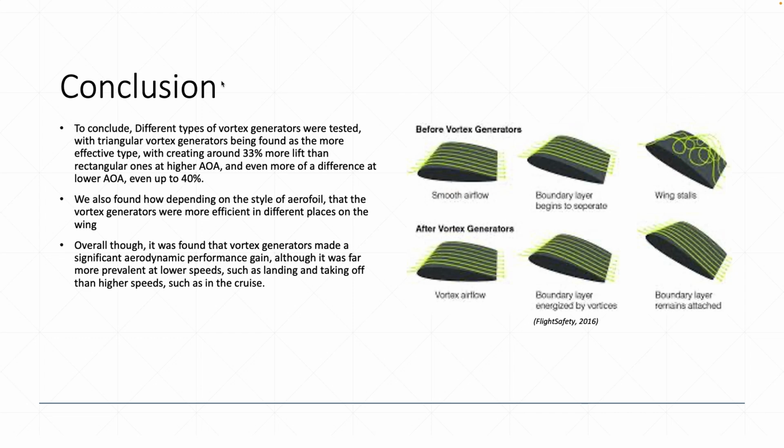So just to conclude, vortex generators provided significant aerodynamic improvement, especially in lift generation. The benefit is most notable at lower speeds, such as during takeoff and landing, where maintaining airflow attachment is critical, as, like I say, you can go at higher angles of attack when you're slower without the curly effect happening from the air separating from the wing and then stalling over the top of the wing. At higher cruise speeds, the benefit reduces, but still offers measurable drag control and also slight improvements in efficiency. Overall, vortex generators are a simple, lightweight, and efficient solution for enhancing airfoil performance in a range of applications.